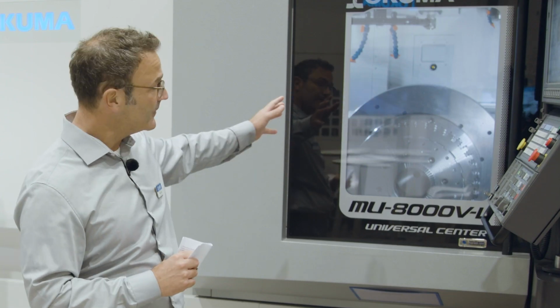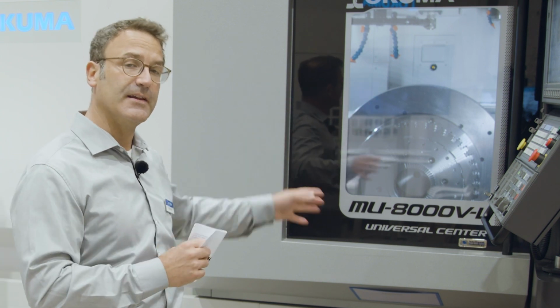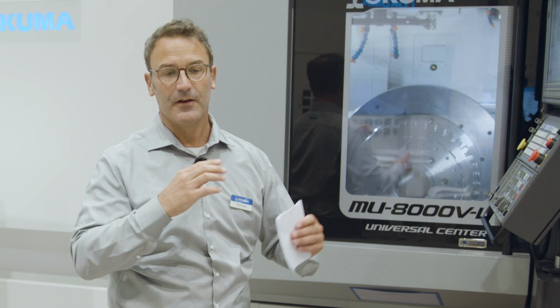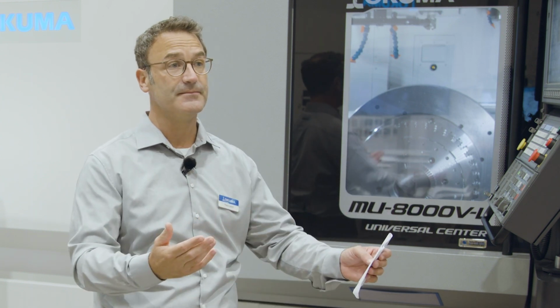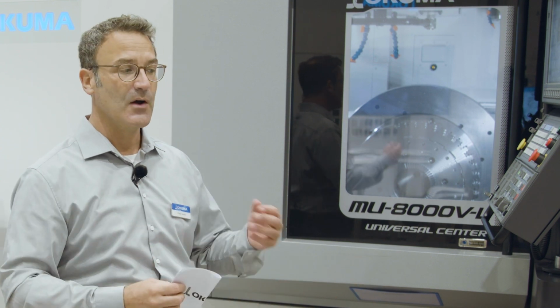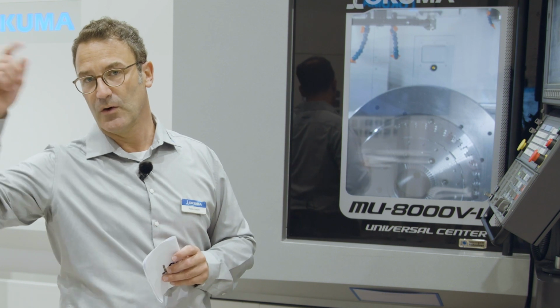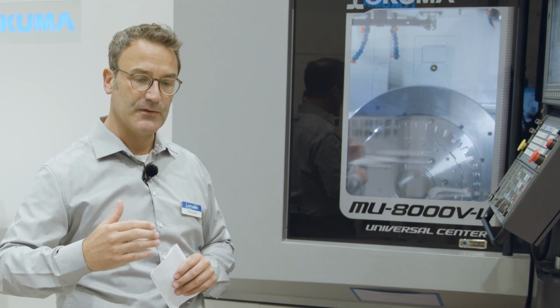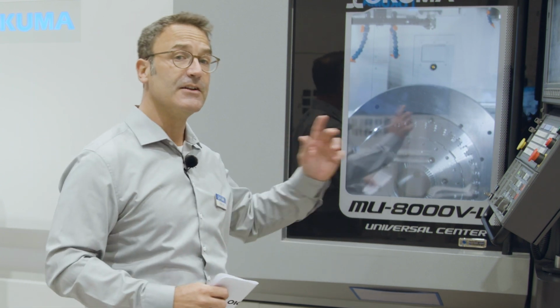Also here the operator-friendly aspect is the drive of Okuma, and therefore we have, for example, our intelligent technologies. One of them is called Servo Navi. As you can imagine, we can have up to 700 kilos on the table. If we have a swivel axis with 700 kilos moving, the acceleration and deceleration will be adjusted to the maximum weight. What happens if I only have 100 kilos? We are losing the acceleration and deceleration which the machine could do without destroying itself. Therefore Servo Navi, just by pushing some buttons, automatically takes the torque of the drives and adjusts it accordingly to the weight on the table. Due to that, we can easily decrease the machining time, because the acceleration and deceleration are much more aggressive. We even have examples from workpieces, from the customer side, with up to 25% shorter machining time just by pushing some buttons.